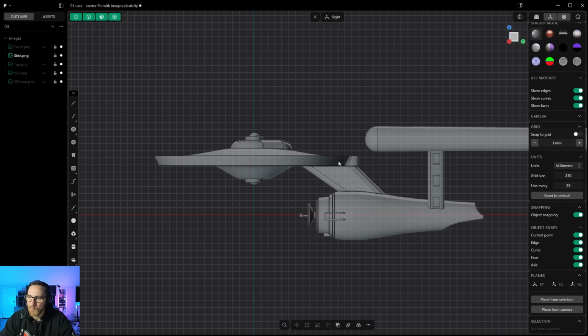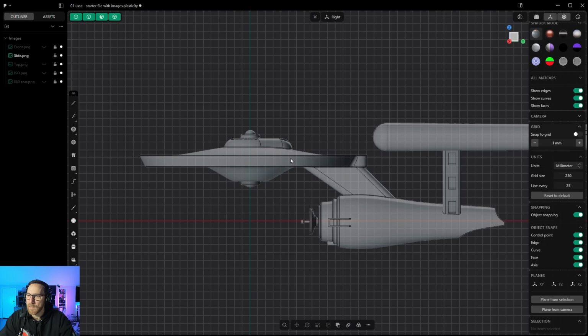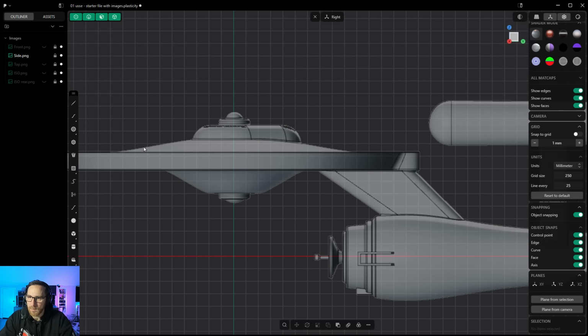But for the most part, if you can get the majority of your geometry in either a revolve or an extrude or a loft or a sweep or something like that, that's usually how you want to start your design and then add or remove from it from there. So usually when I look at a design, I look at the bulk of the geometry and how I can capture that. Now, obviously, if we did this with an extrude, it would be very tricky because we've got some gradual transitions here. We've got dome features on the top and the bottom. And so it doesn't really make sense to try to extrude this. We could probably extrude the disc portion of it. But in reality, a revolve makes the most amount of sense.